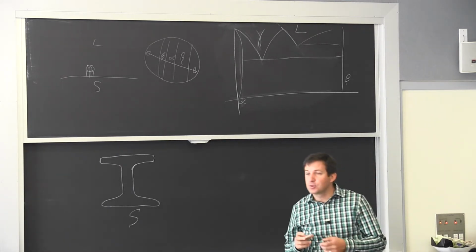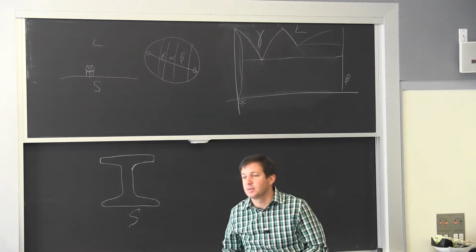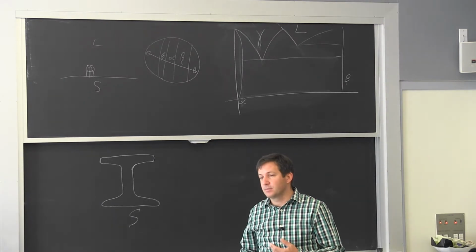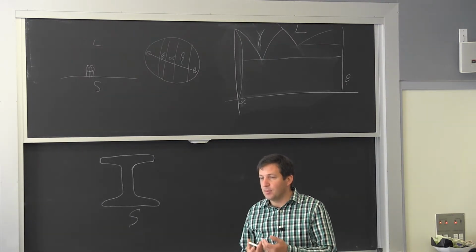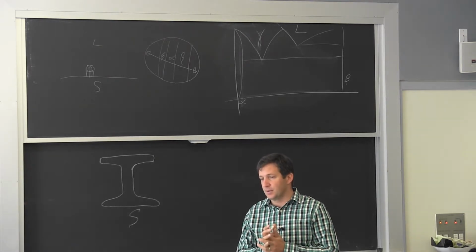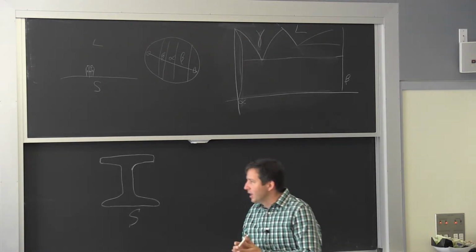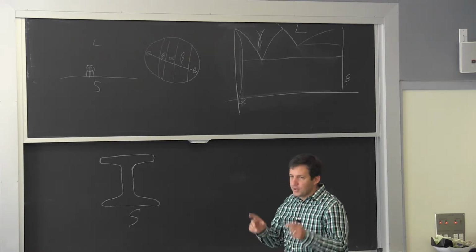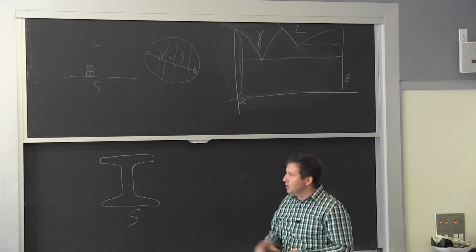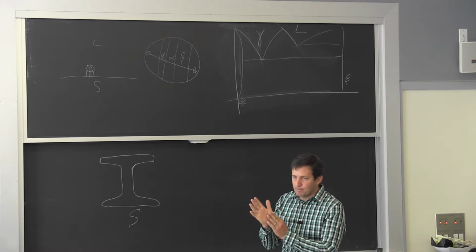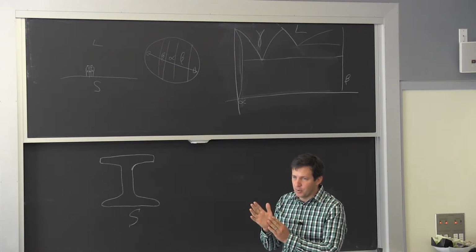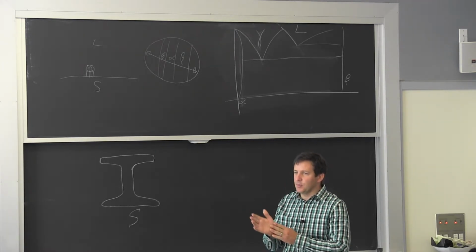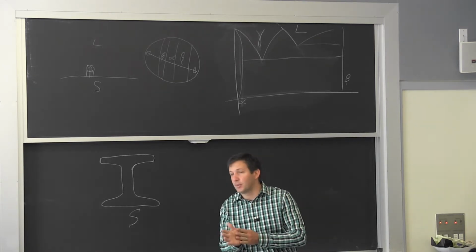If you use cold work products, you have a higher yield strength, but you have less hardening. So by the time you reach that critical shear stress, it's going to fracture more easily. I'm not sure we use it too much for shearing. On a professional shearing machine, you can really minimize the burr by tightening the distance between the two parts to something that most people will not consider a problem, I would say.